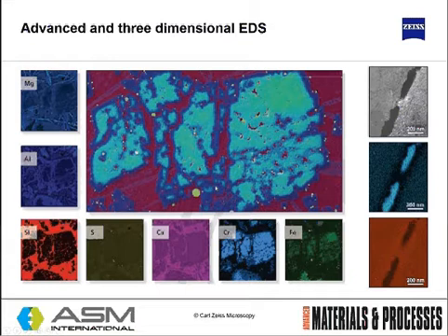By segregating the data from different wavelengths of emitted X-rays, you're able to assess that this inclusion is chiefly a chromium inclusion, but you're also, from these bright spots, able to determine the location of iron within those inclusions. You can also see these rather dendritic growths, which are high in magnesium within that sample. So it's a very powerful local elemental analysis technique.